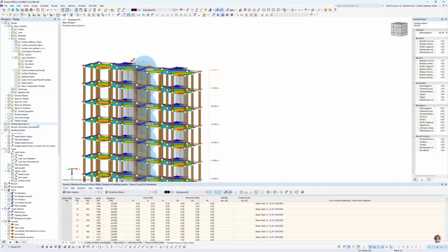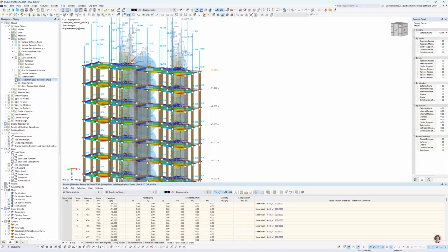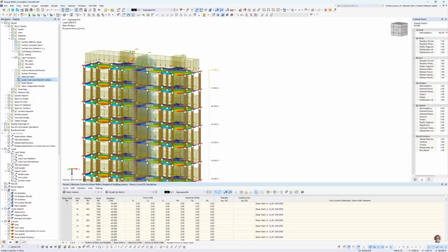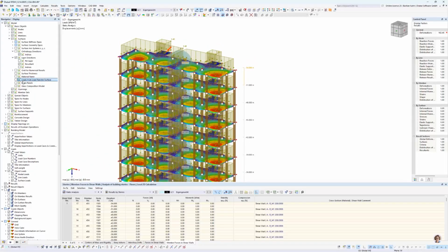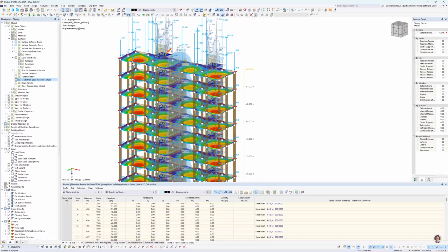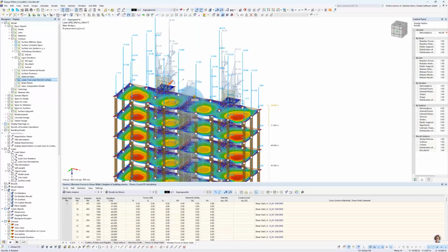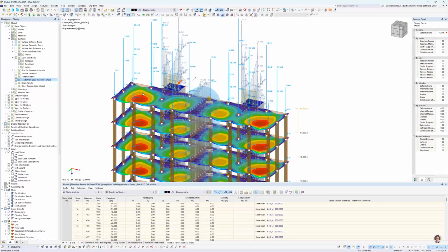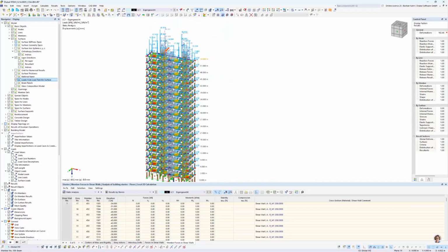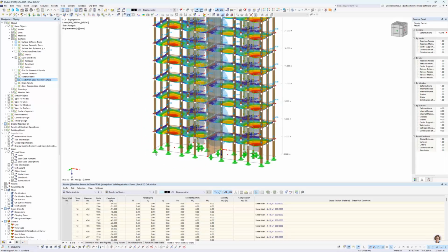And maybe we go to loads from transfer surface and show that again. So then go like this. And you see there's a force of 3.4 kilonewton per square meter on it. And we define loads from transfer load surface. You see that the load from the first story is summarized here and transferred to the other. And this will then also regard the settling that I just defined via this option that we had.